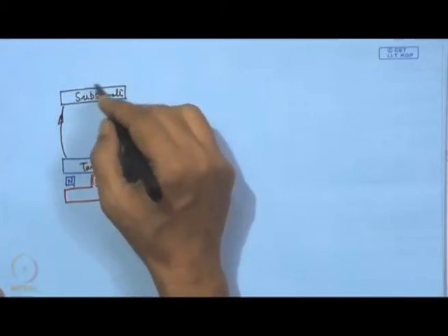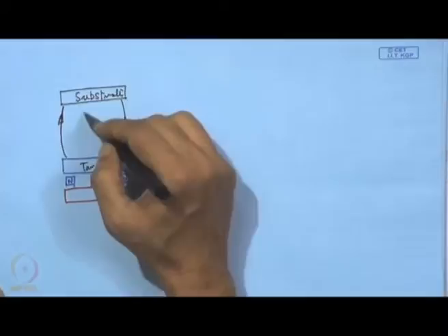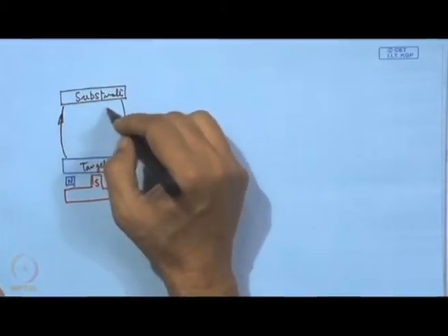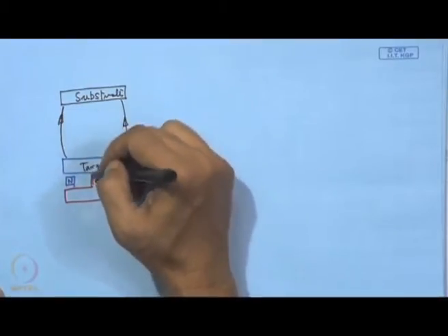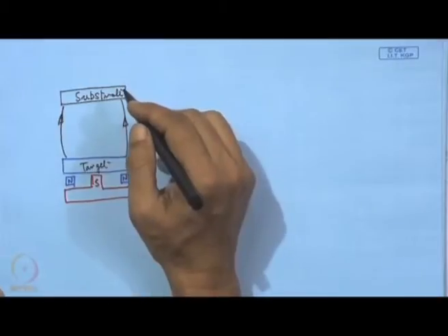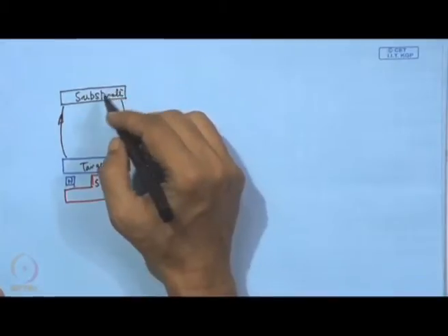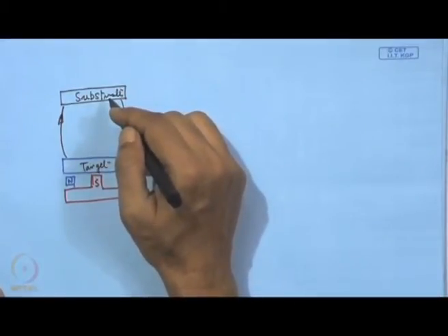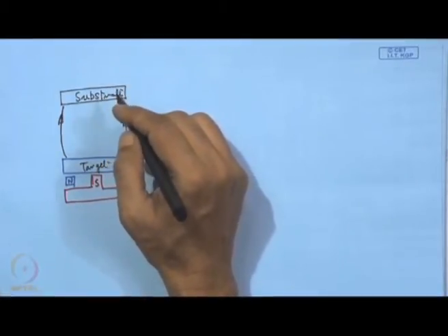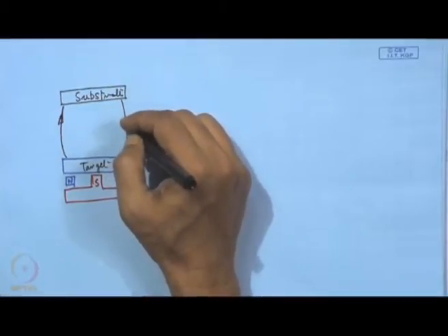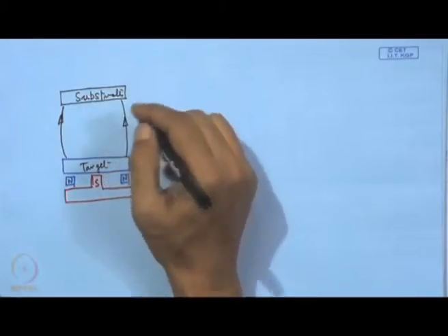Even if the substrate is rotating, then what will happen? In one cycle, in half of the cycle, one semicircular portion, one half circle, will be exposed to this sputtered flux, while the other part will have a shadowing effect, and this will have an immediate influence on the property of the coating. So, this has become one of the greatest limitations of this single target unbalanced magnetron.